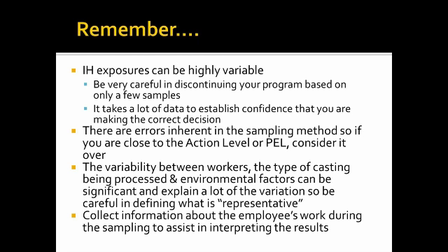Another thing I think it's really important to do is collect information about what that person was working on the day that the samples were taken. That can be invaluable information when you're trying to set up controls or trying to make decisions on what to do about an exposure. It's very important to know what that employee was doing. Maybe there's some unique casting that causes all your problems and the rest of them don't. So it's important to know that sort of thing.